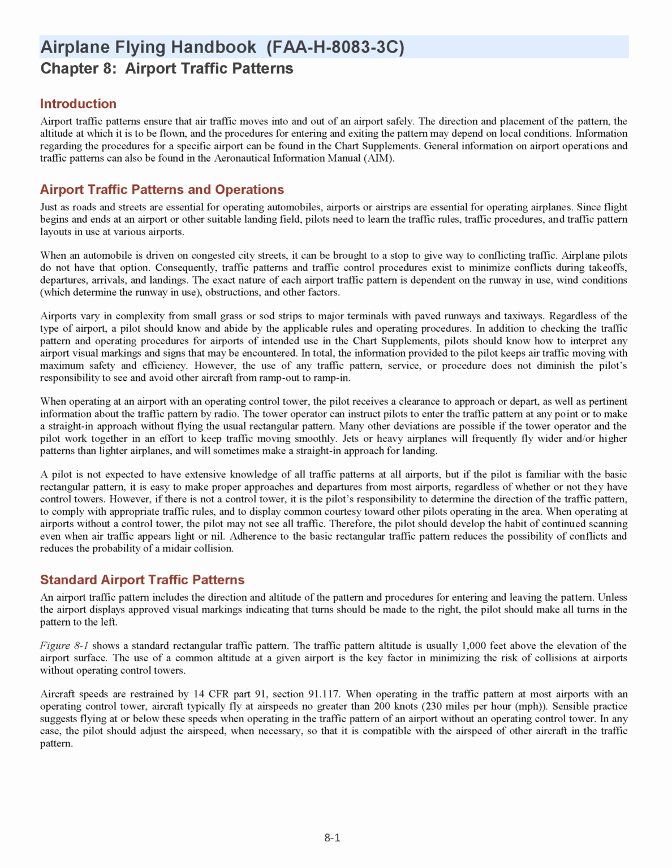A pilot is not expected to have extensive knowledge of all traffic patterns at all airports, but if the pilot is familiar with the basic rectangular pattern, it is easy to make proper approaches and departures from most airports, regardless of whether or not they have control towers. However, if there is not a control tower, it is the pilot's responsibility to determine the direction of the traffic pattern, to comply with appropriate traffic rules, and to display common courtesy toward other pilots operating in the area.